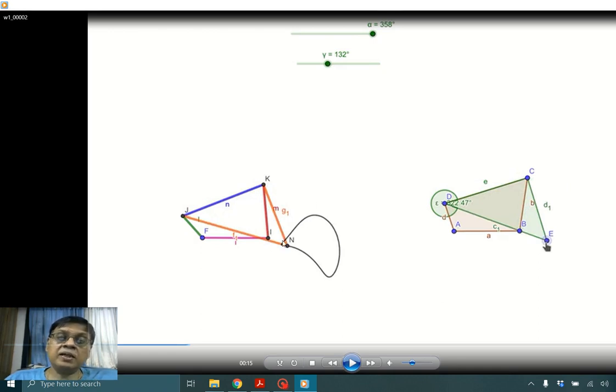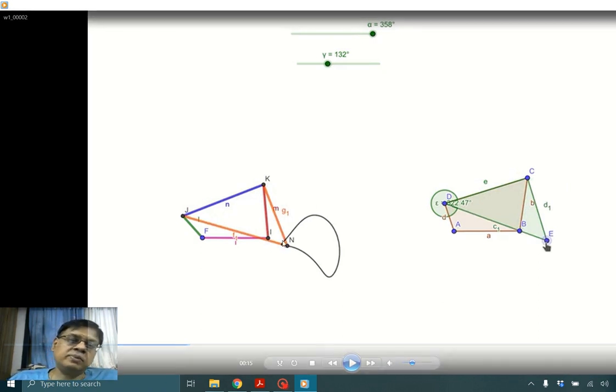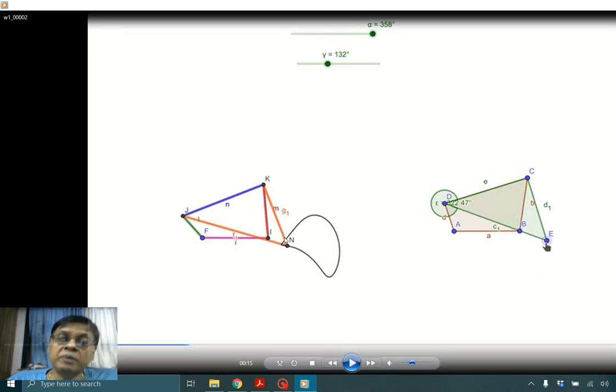So, I could randomly do this and then come up and say, look, if I were to use this portion for my path generation, you can see here that it is more of a straight line than what I came up with, and you can also see this is somewhat circular, so I can use three precision points to go through a circle like this, and I can use this to go through a straight line like this. So this is one type of coupler curve that you can get.